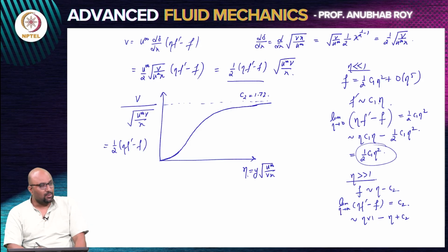So, this is an interesting observation that the vertical velocity within the boundary layer doesn't vanish at the edge of the boundary layer. When we started this whole discussion, I said we have these three boundary conditions. The surface or the plate is no slip, no penetration, and the streamwise velocity should match the free stream velocity at the edge of the boundary layer. We didn't apply any boundary condition on the vertical velocity at the edge of the boundary layer. So, now what we have observed is that the vertical velocity at the edge of the boundary layer is actually non-zero.